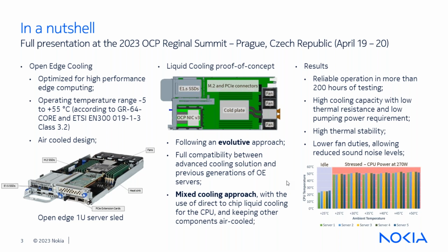Yeah, in terms of energy efficiency, this also relates to the fact that we are looking more into warm water cooling, not so much cold water cooling. Basically, we have better efficiency if we're pumping water at a little bit higher temperature. For example, if the liquid is kept at 40 degrees, then everything is controlled, and we do not reach CPU temperature above 60 degrees, so it's still quite cool, not overcooled yet.